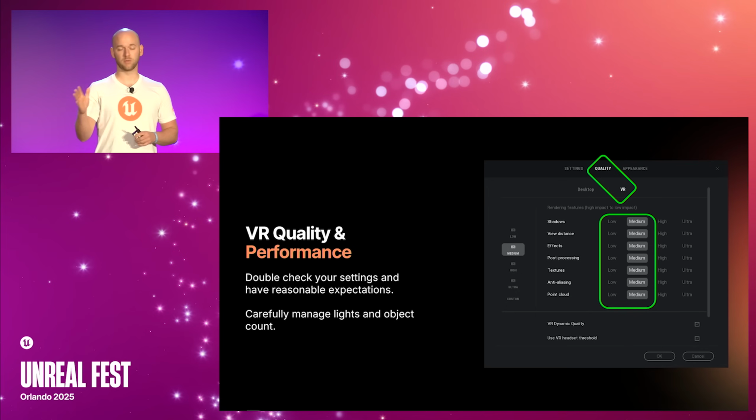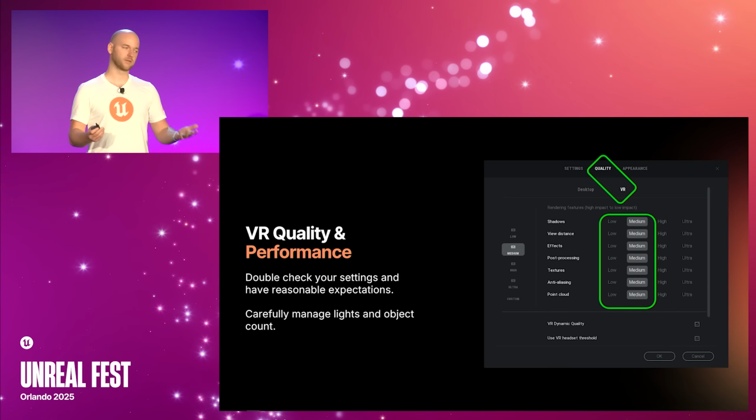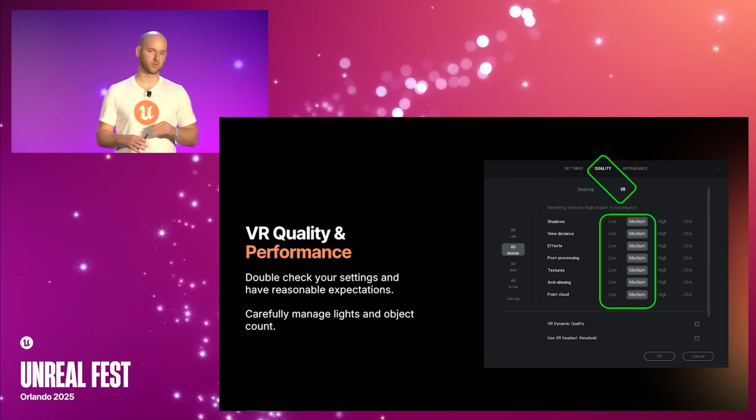So I recommend going to medium and potentially even low, because Twinmotion focuses on great lighting, lots of dynamic objects, dynamic shadows. Those things are really impactful to VR, so you should be expecting to turn off some of those features to have a really smooth, comfortable experience.